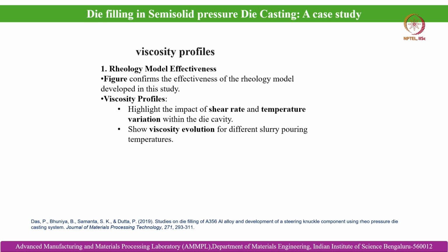So basically, it shows the rheology model that is developed in this case study, like what we have discussed before, and further details can be found in this publication. This confirms the effectiveness of the developed rheology model used for die filling studies for Rheo die casting, and the viscosity profiles highlight the impact of shear rate and temperature variation within the die cavity.